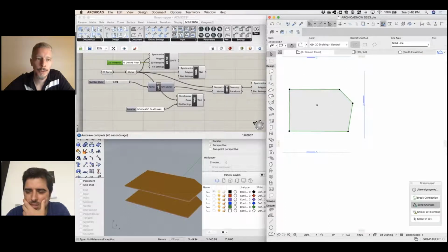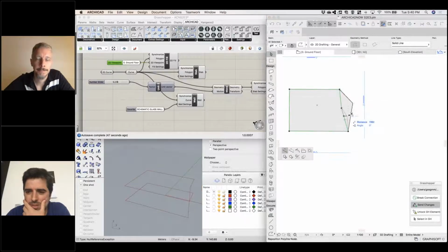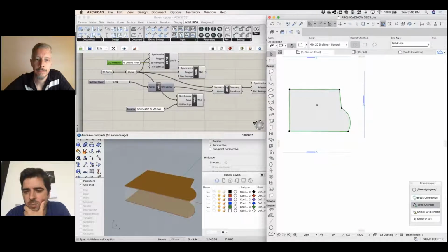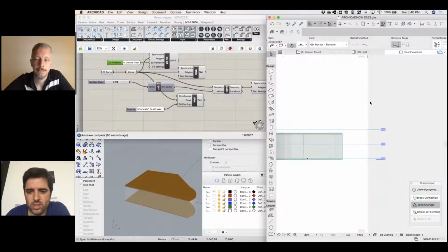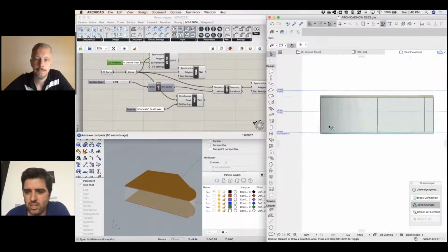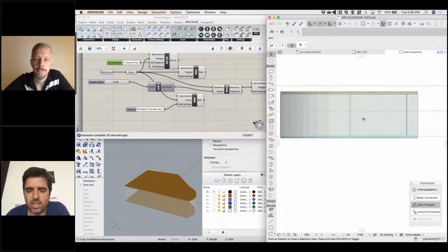Yeah, and you could also curve those edges as well, Marcelo, or add points. Yeah, as James mentioned, I want to curve. I can just curve it here. And a wall can be curved, a slab can be curved with a curved edge, so it's not a problem. So if I open this from this view settings here, you can see even the curve represented inside Archicad.